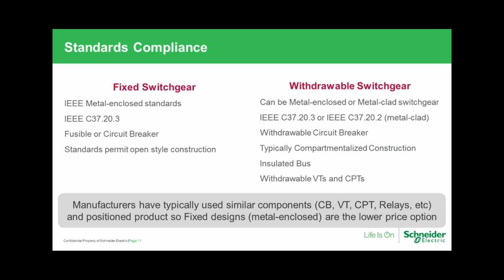So traditionally, a metal clad switchgear is going to be withdrawable. It's going to be compartmentalized to isolate all the components such as the instrumentation, your main bus, and both your incoming and your outgoing connections.